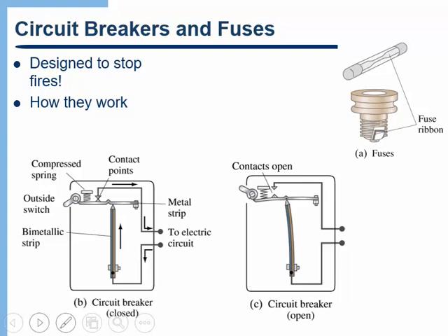And as we'll see in just a second, most of the circuits in your home are going to be either 20 amp circuits or 15 amp circuits. So if you draw more than that amount of current, the circuit breaker opens up.